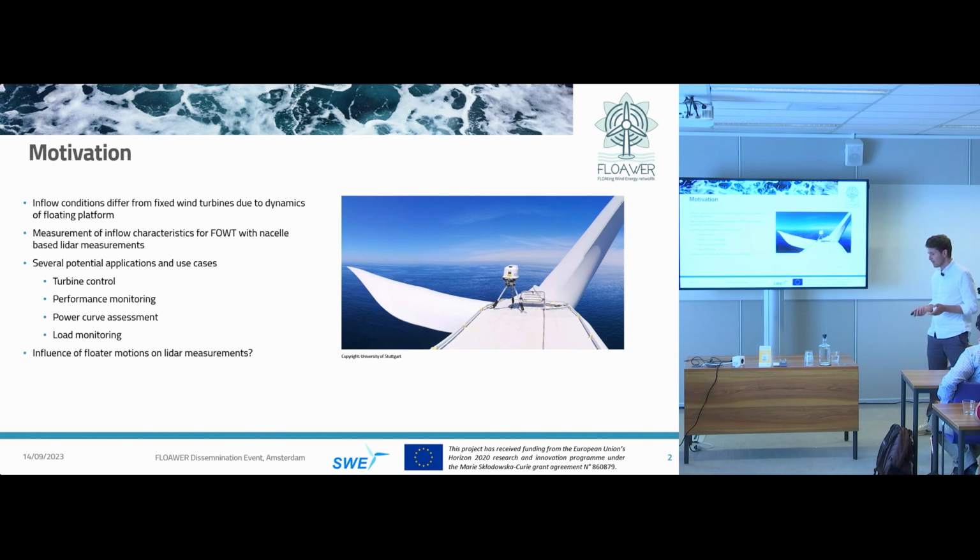A little bit of motivation, why this is interesting or why we looked into that. Inflow conditions, as you can imagine, differ for floating wind turbines from those with fixed substructures due to the dynamics of the floating platforms. And if we want to measure the inflow of floating wind turbines, we need to be aware of that and see what kind of influence there is from these motions on our lidar measurements.